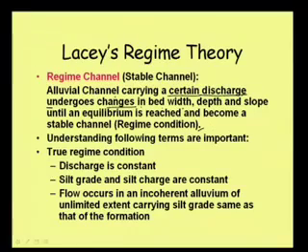Of course, if the sedimentation takes place at the upstream itself, then all sediments are getting deposited at the upstream. Then when all sediments are depositing at the upstream and downstream is getting free of sediment, again that water may start eroding, and that way slope can increase also. So, this change of slope will continue. This slope is also getting adjusted, until an equilibrium is reached. Finally, it will reach an equilibrium and become a stable channel, and that channel is called in regime condition.